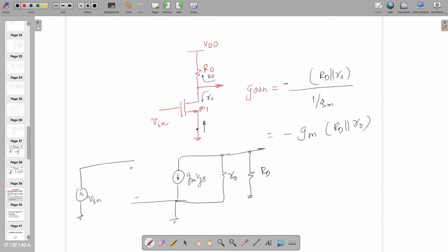Right? So you can always apply the Thevenin theorem and find out. RD will of course always be in kilo ohms. Have you ever connected RD or RC in ohms? No, right? If you are connecting RC in ohms, then there is a problem. Then it cannot drive, and this becomes current as output. So sorry, voltage as output, right? Not current. So it is expected that RD will be in the range of RO at least.